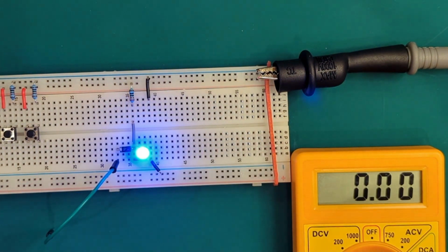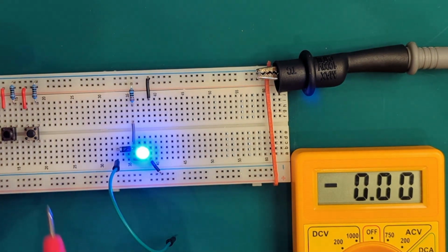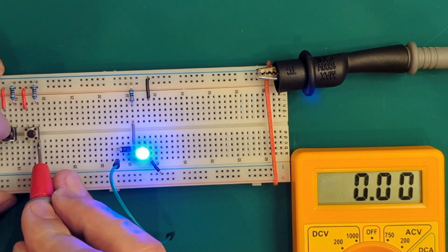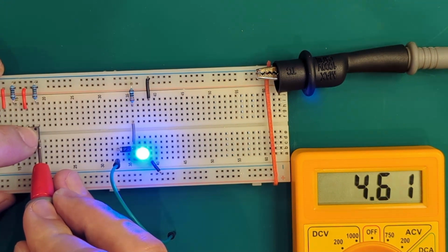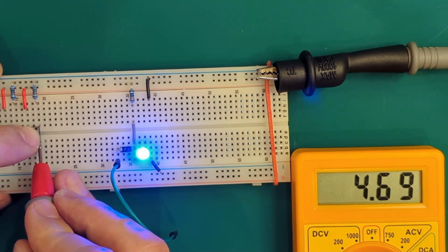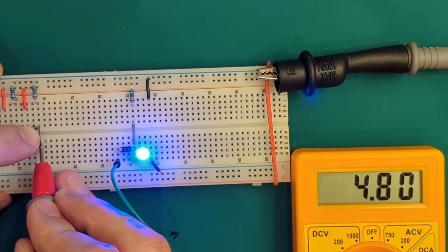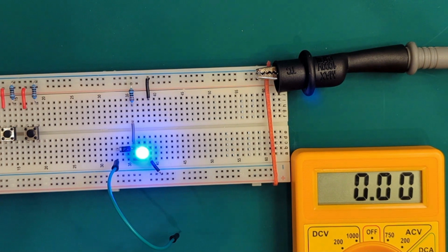When we had the green LEDs, it was working. And actually, if I unplug this, let's measure. Now I have 0 volts here, and close to 5 volts when it's pressed. It's a bit wobbly and the number changes, but it's still pretty decent. So both parts work by themselves, but they don't work together. Let's try to understand why.